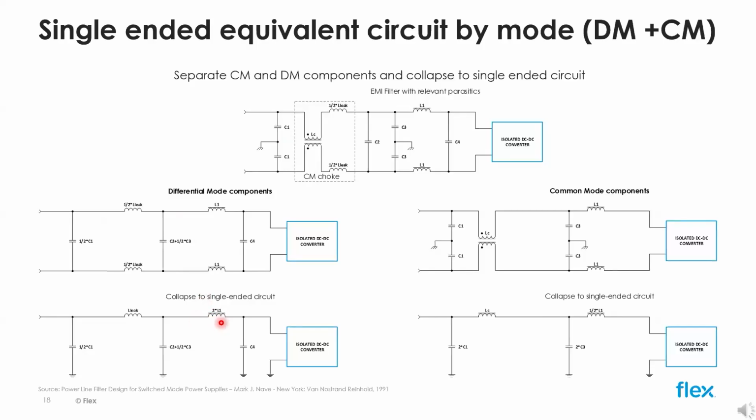Similarly, for common mode, we use the common mode inductance and we can eliminate leakage inductance and all the X caps. In this case, we have two differential mode inductances, basically two discrete inductors, each with its own magnetic core, placed on both lines. The two inductors are parallel for common mode noise, and this is reflected by half inductance value indicated in the single-ended schematic.